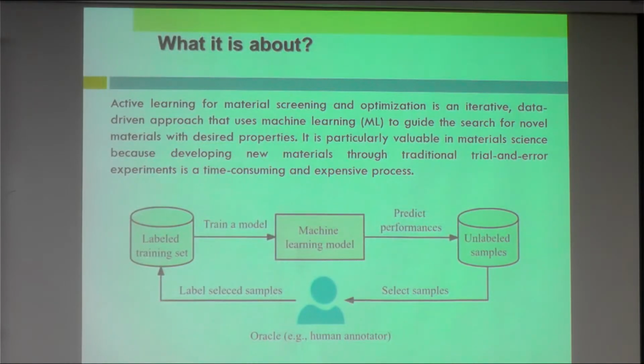In the case of a solder alloy, you might want a certain melting point, which might be around 220 for SAC solder alloy. Then you try to predict the melting point if you add another material to it, and depending on your application, you want to know the tensile strength and the Young's modulus of the materials, etc.